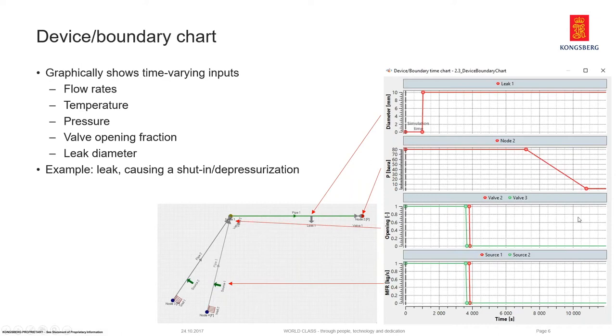I can also mention here that we're only showing the time-dependent input in these plots. The reason for that is that if you have a very large model, then showing all of the constant inputs would just clutter up these plots. So we've limited it only to the time-dependent variables. And when you modify your model, these are automatically updated whenever another variable becomes time-dependent or if it's removed. So this plot, you can have it open while building your model, and it will be dynamically updated.